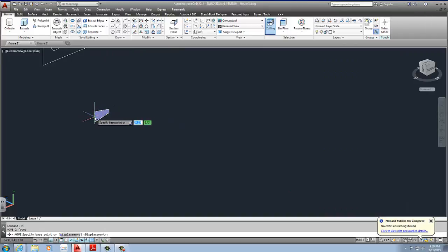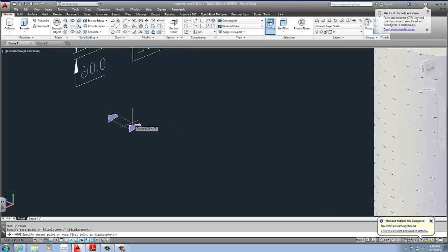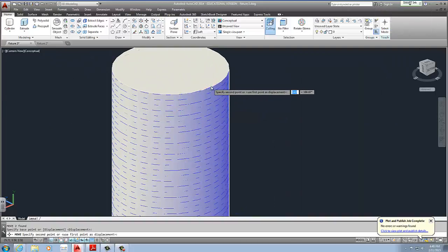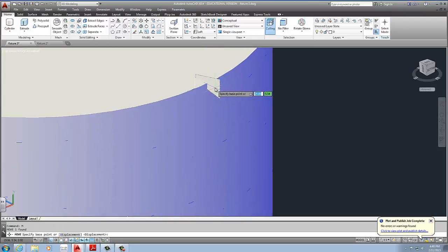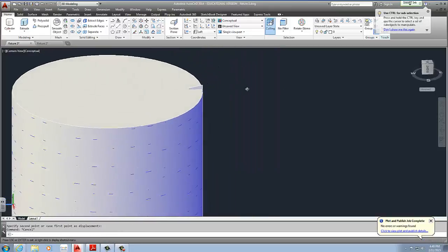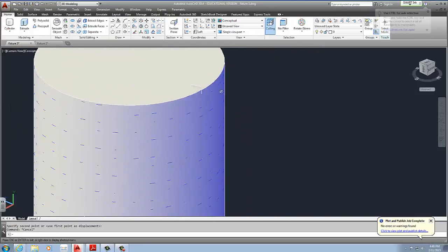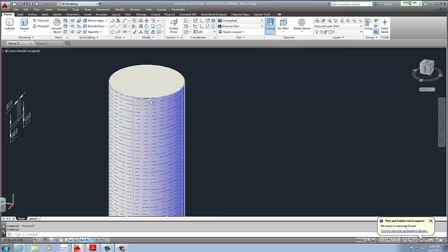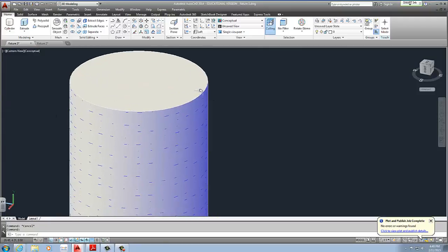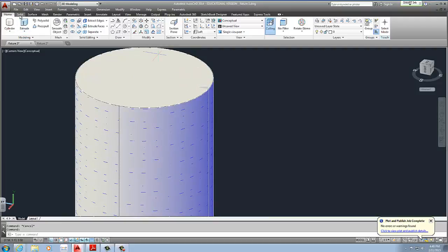So I'm going to move this over, and I'm moving it based on the back, the larger vertical line, center point. I'm moving it over to that place, and this is where I need to rotate it using the rotate gizmo to adjust it once more. So I have something like this, and I'm going to have to make one more thing with this before I start doing the, well, actually, yeah, no, that's fine. So what we're going to do next is use the sweep command.